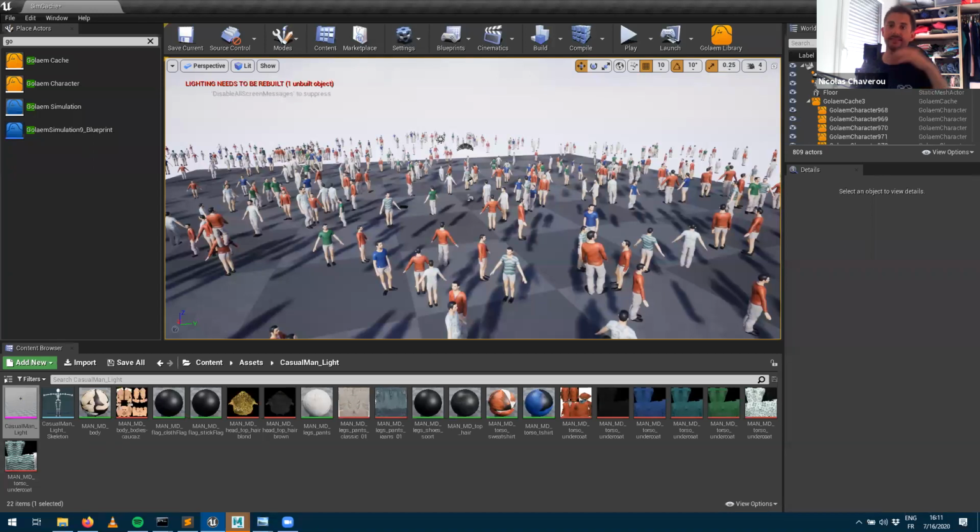Otherwise, you've got the second interaction, where you have your fluid simulation, which has been made already, and you want your characters to react to that. You can just bring that in as an Alembic particle cache within Maya, and you can react to this. So we are taking into account particle fields. If you want your characters to move with that fluid, that's something which can be triggered. You can control the force behavior, the one I've been using before to push my characters up. You can use your wave or your fluid simulation as a source, and we fetch the different magnitudes, the different forces, and apply that to the different rigid bodies.